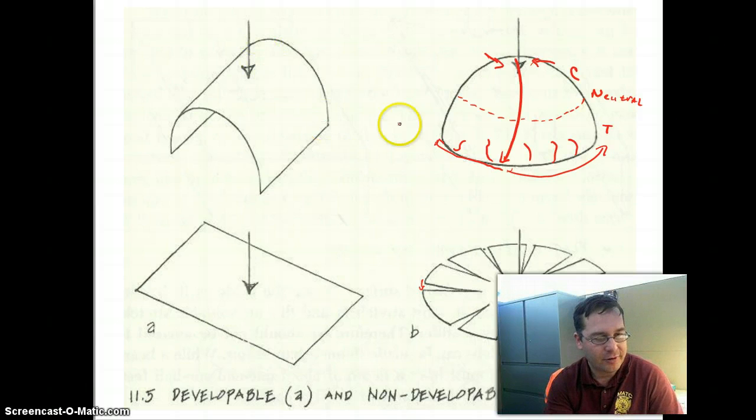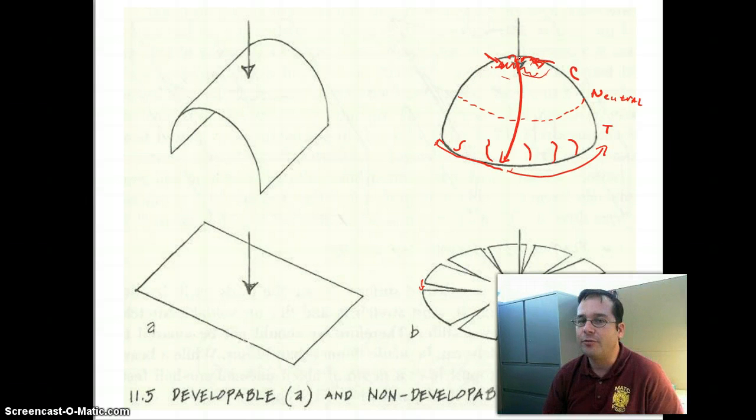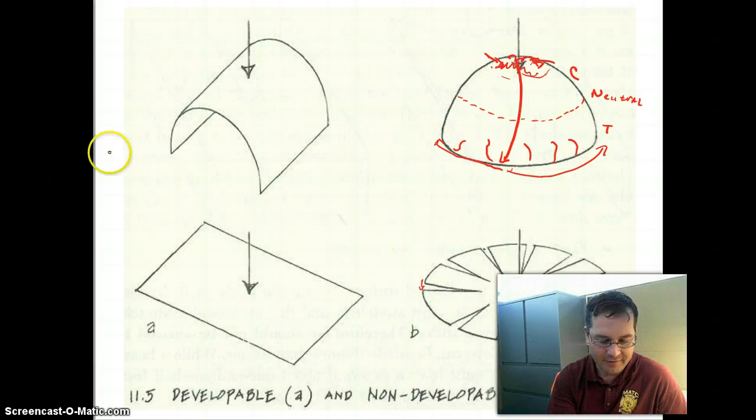Well, you can imagine that if your car door has this nice non-developable curve and someone puts their foot in it or something and pushes it in, what's got to happen is near the vertex of the curve, that metal is under compression, but sheet metal doesn't handle compression very well, and you get wrinkles in the metal. And so once they've dented your door, if the metal has become wrinkled, there's no way to repair that really. The other possibility, depending on how the dent proceeds, is you may stretch the metal that is under tension. And there is actually a strategy for that.